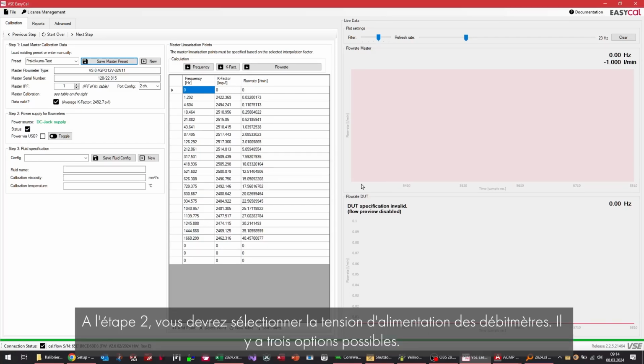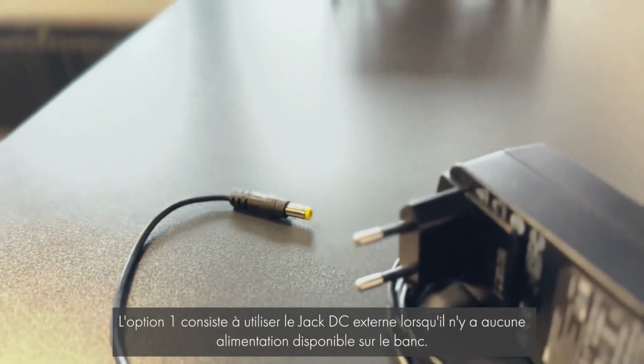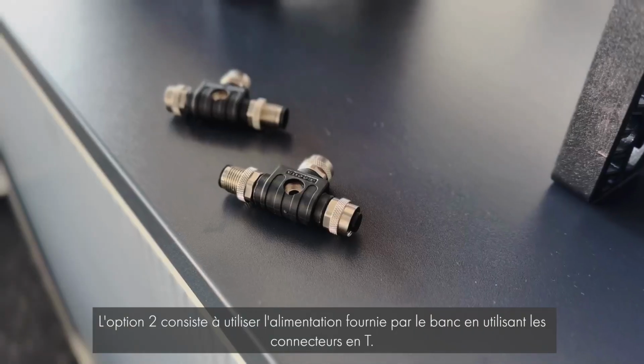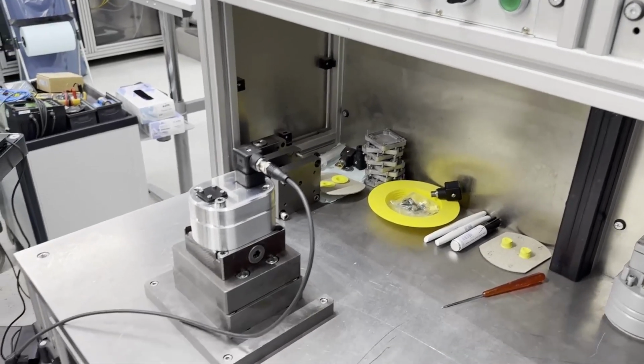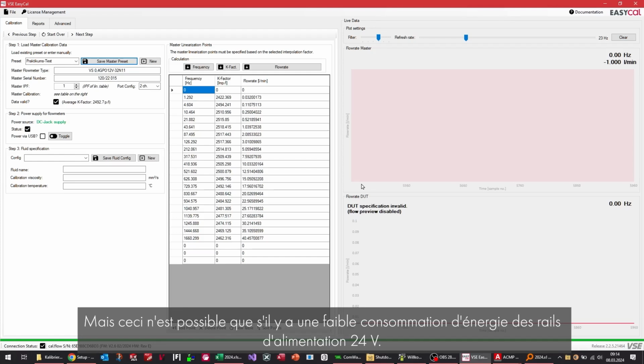In step 2, you will set the power supply for the flow meters. There are 3 different options. Option 1 is using the external DC jack supply when there is no supply on the bench. Option 2 is using the existing bench power supply using the T connectors. The last option is to use the internal boost converter, which converts the 5 volt from the USB into 24 volts, but this is only suitable if there's a low power draw from the 24 volt power rails.